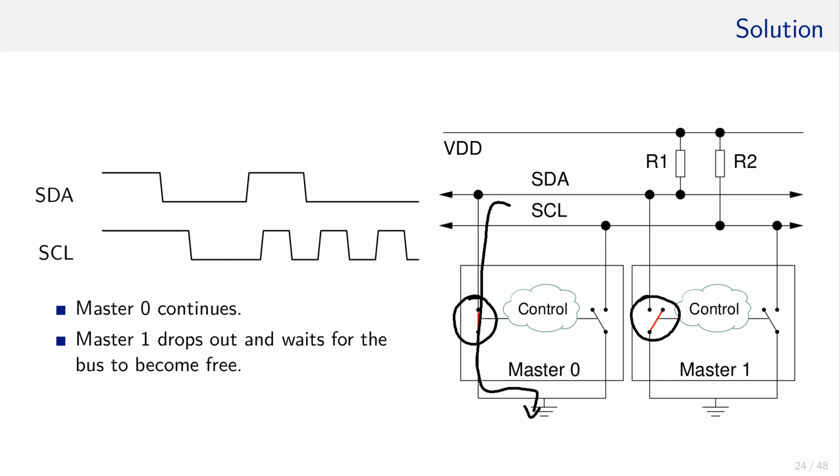Both masters sense the SDA line for instance, the acknowledgements and data coming from the slave. However, if a master writes to a line, the same mechanism is also used to listen if the written value matches the read value.